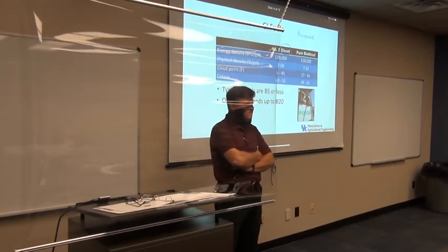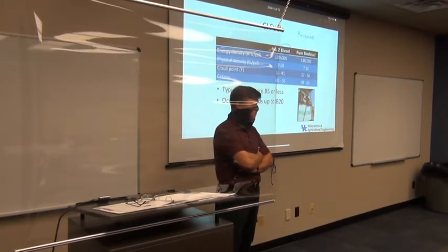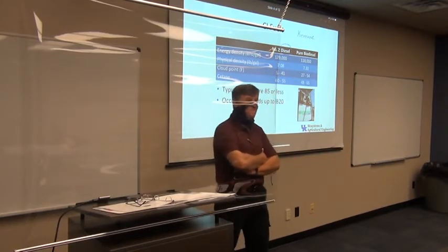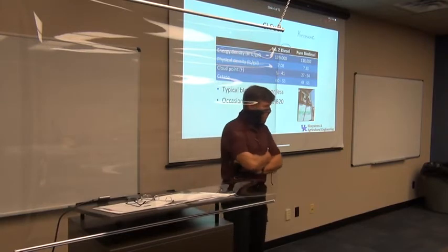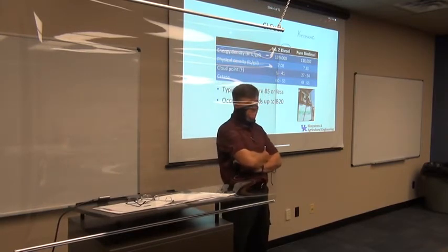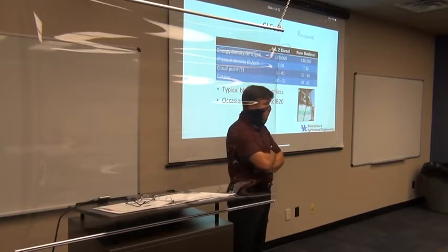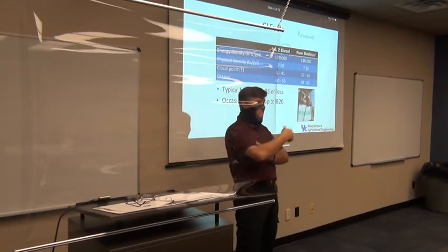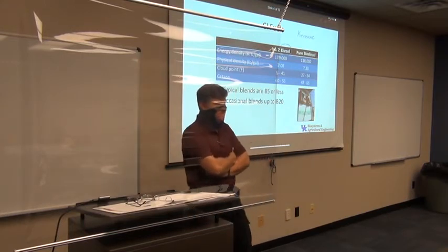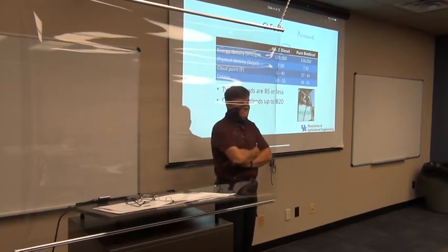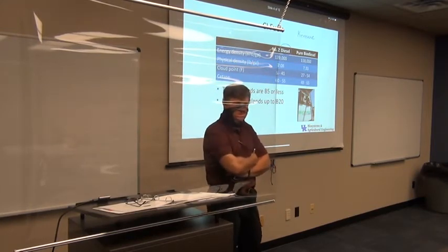What do you think? Fuel clouds up. Actually, we talk more about it gelling up. I grew up in a more northern climate in Pennsylvania, so we had trouble in the wintertime with our fuel gelling up, which is basically the same thing as clouding up. So what is it, Trey? You're shaking your head. It's basically diesel: if it gets too cold, it starts to turn into a solid instead of a liquid. Yeah, so it freezes, basically.